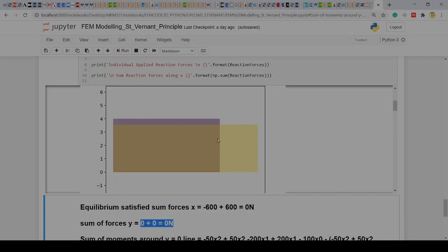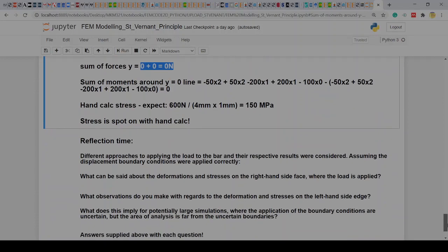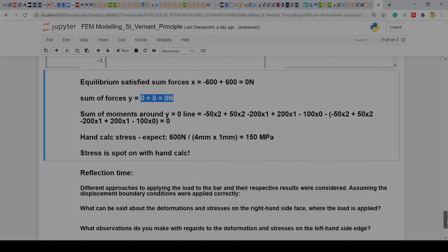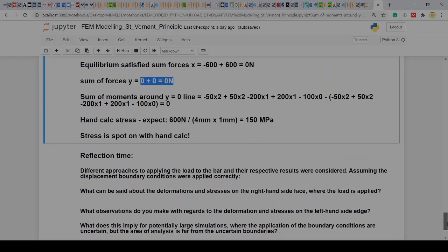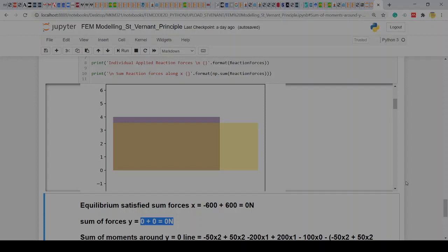So if you introduce some variation here, that variation will dampen out as we move along spatially, which is different to hyperbolic kinds of equations where those variations might actually propagate. So please bear in mind, this is a structural mechanics phenomenon. It depends on the partial differential equation you're looking at whether Saint-Venant's principle counts or not. That's just another important consideration.